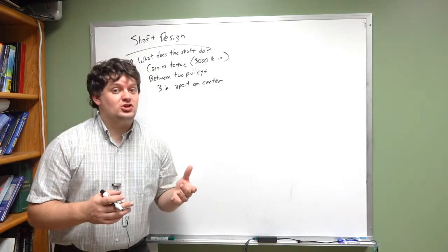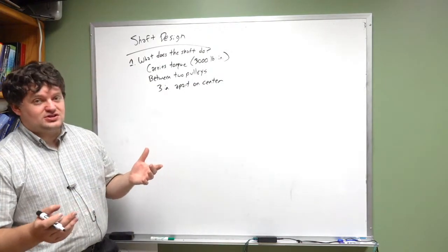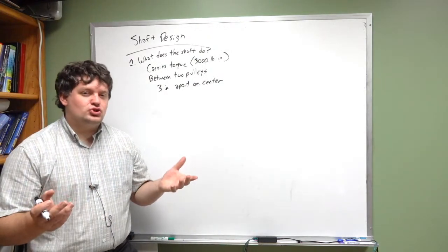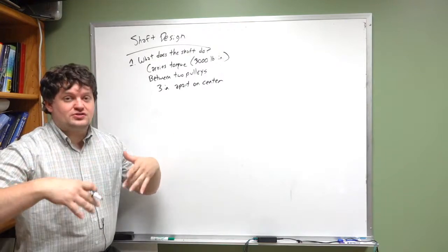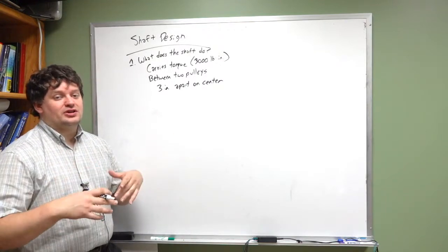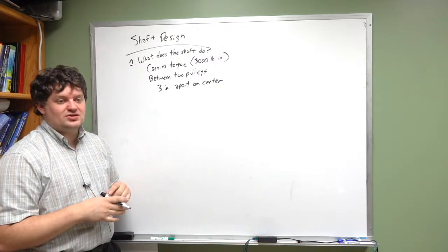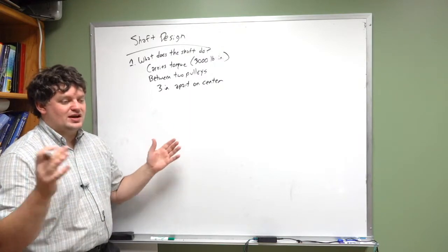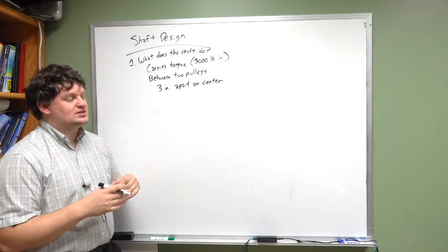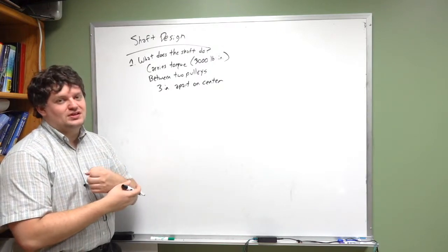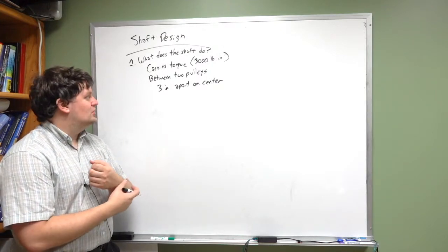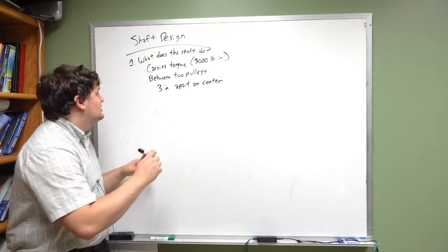If you have really, really long shafts, then you could consider having 3, but having 2 allows for flexure of the system. Flexure of the system usually just means the bearings rotate inward a little bit. You don't have issues with residual stresses or axial stresses.